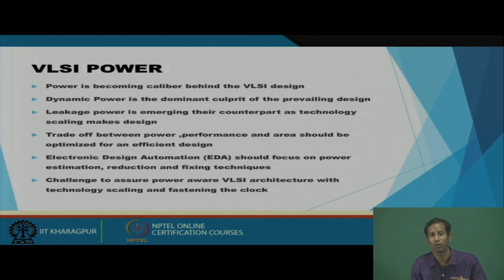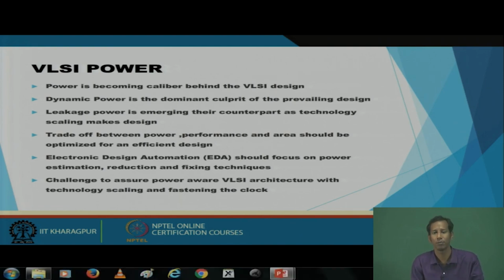That means you do not have to bother about needing this architectural optimization. Whatever the EDA tool designer can do manually, they have tried to do automatically. For the logical optimization, they have already provided the algorithmic form in the EDA tool, whenever you do the synthesis. Synthesis means your logic part will be converted into the corresponding gate level. At that time they run architectural optimization, gate level optimization and logic level optimization. They come up with the optimized expression which will be represented through gates. The EDA tool has developed so far that it can do this automatically.